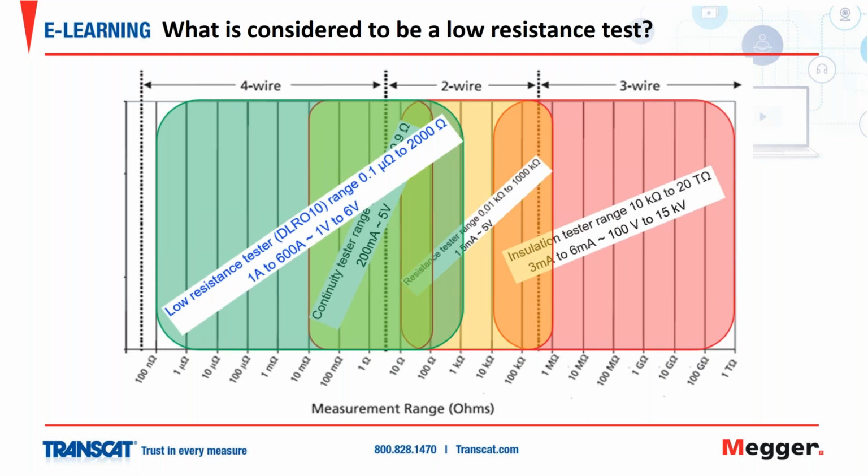In general, low resistance tests are considered to be below 1 ohm. Again, they use a higher current and a low voltage in order to read very low resistances, all the way down to 1/10 of a microohm. This is a 4-wire test. The reason for this is it removes the effects of contact resistance and the test leads. A 4-wire Kelvin measurement makes it possible to accurately measure resistance values that are less than 0.1 ohms by eliminating the inherent resistance of the lead wires that connect the measurement instrument to the component being tested. So again, these are reading things much lower than a continuity tester.